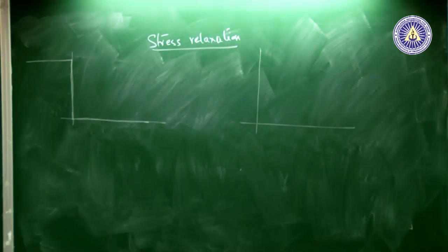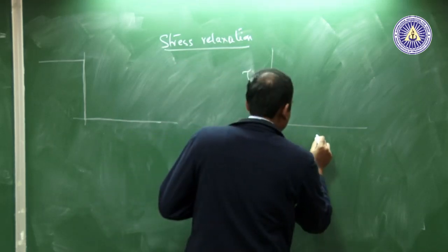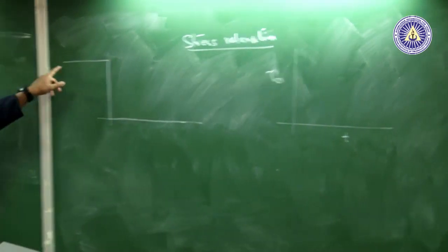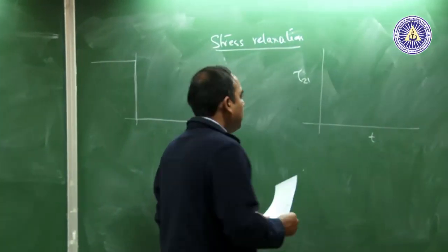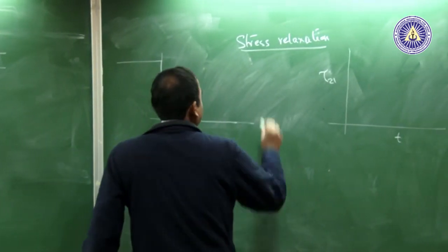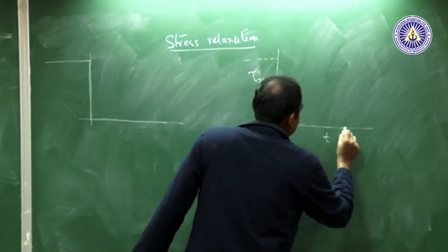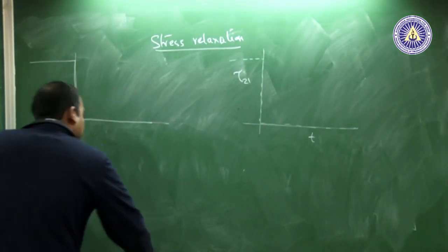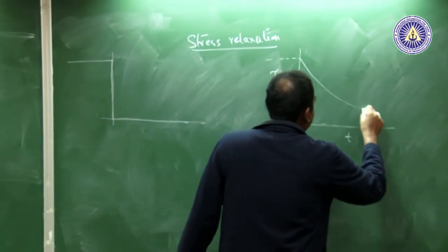So, in stress relaxation, you are suddenly releasing the stress, which is why it is called stress relaxation. And then if you notice the response of the stress, since it had an earlier steady state, the stress was at an earlier steady state value. If it is a Newtonian fluid, it would simply follow the strain rate, which means for a Newtonian fluid you will just get this sort of a curve coming out. However, again for a non-Newtonian fluid, you will actually have a lot of transients, which means the curve will now for a non-Newtonian fluid be like this.